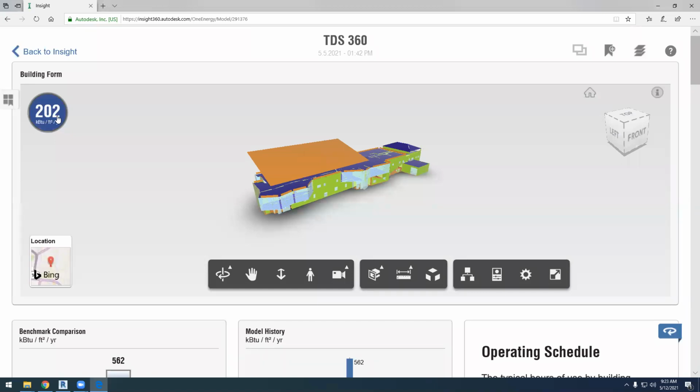I told you that if we visit the Passive House Institute, we have like some reference here, depending on where our location is, we are allowed to spend this yearly energy per square feet, and we have to divide the total energy by the square footage of the building, because then we can compare different buildings, because of course larger buildings will consume more energy. Okay, but if we want to analyze the quality of the construction, we have to divide this by the square footage of the building.